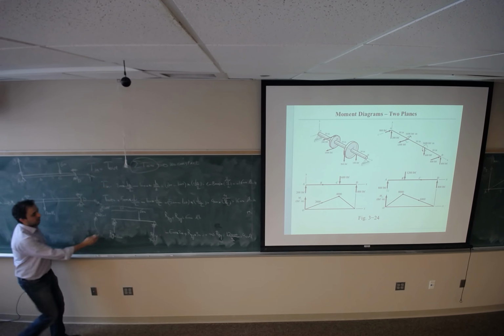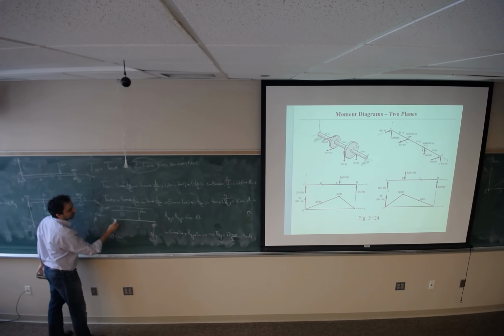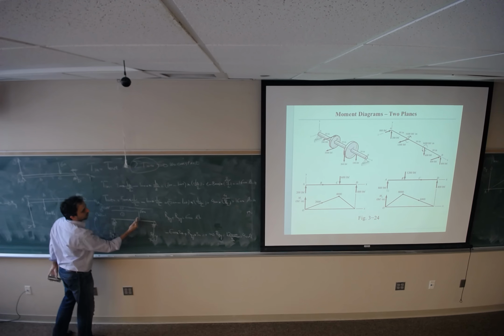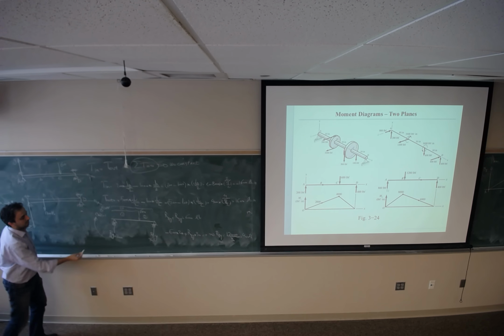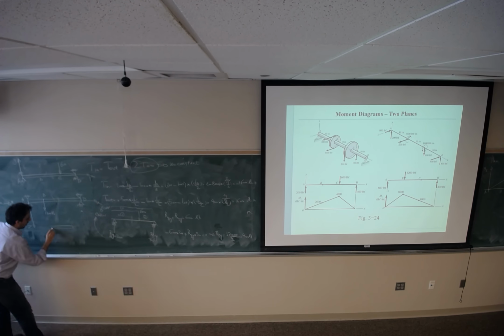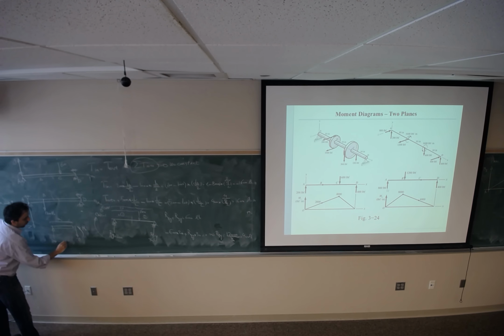Then I will look at the beam. I start from here. I label this as section 1. It goes up to the first point, the first force that you will see on the beam. And after that, we are going to have the second section. We cut it at the distance of x. 200 here. This is x. This is V. This is M. Solve for V and M.